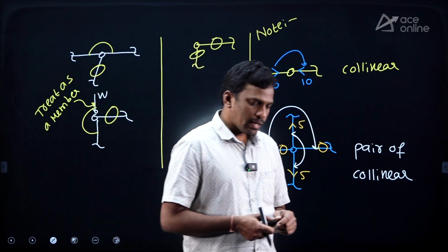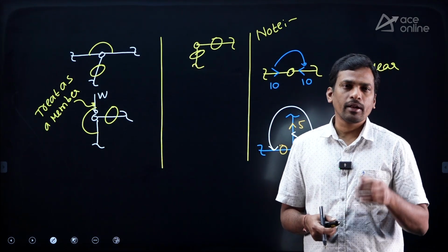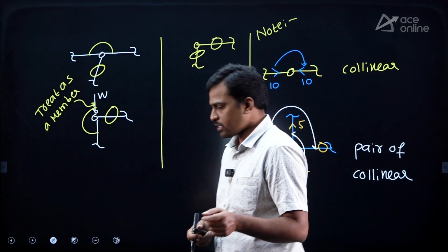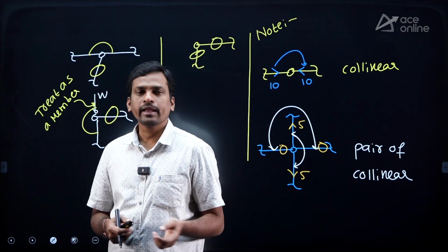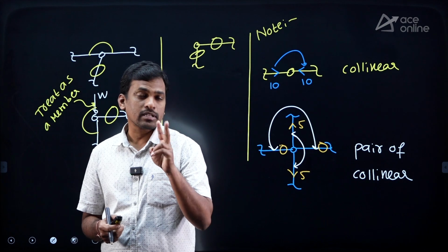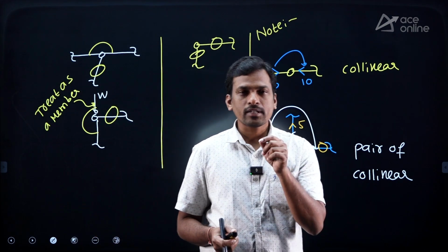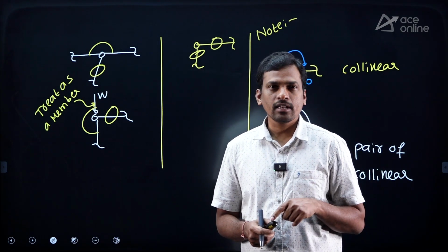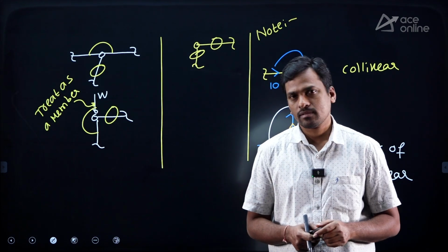Students, I told you the complete topic of method of section depends upon how to cut the structure. You can cut the structure horizontally, vertically, inclined, in a U or V, or any zigzag shape. But 2 conditions must be satisfied. What are the 2 conditions? First condition: the section should pass through the selected member. Second condition: the section should divide the entire structure into 2 separate parts.